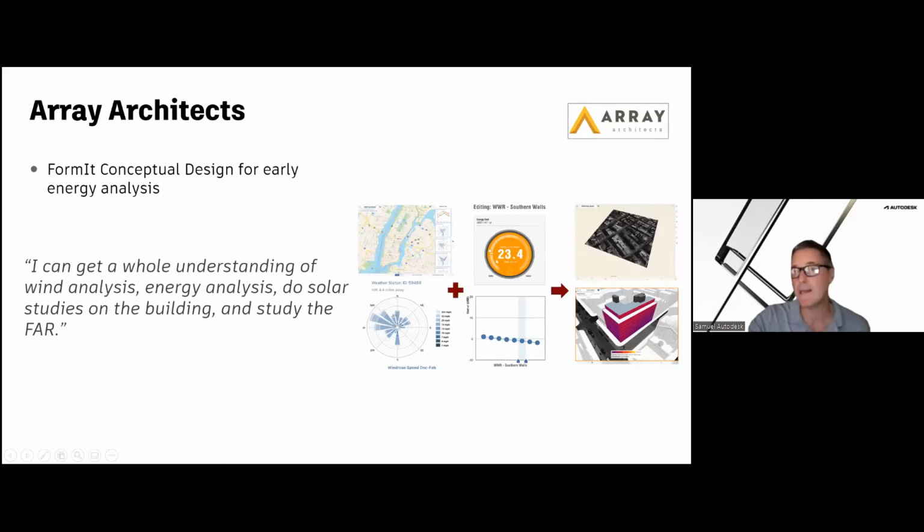You can quickly knock up a design. You can start to look at EUI information to see how it's going to perform. You also have data that it pulls down from the cloud, like the aerial image, and you can run the solar analysis tool here in the bottom right to see the radiance on the facade of that design.